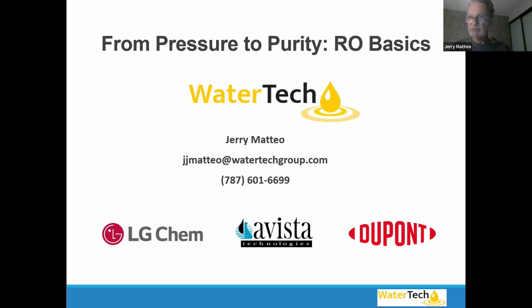In other words, the membrane will reject it, but it doesn't disappear. Remember, I only have 3 streams: feed water in, good clean permeate product water out, and concentrate out. Concentrate is all of my remaining material that didn't go through the membrane. So even if the microplastic doesn't go through the membrane, it's going to be in the concentrate. Now, in a small system, in an industry, we could probably handle the concentrate some other way. And I do not believe, because it's almost like a layer of paint, that the membranes add to microplastics, but I never had that question asked before. So I'll dig into that a little more.